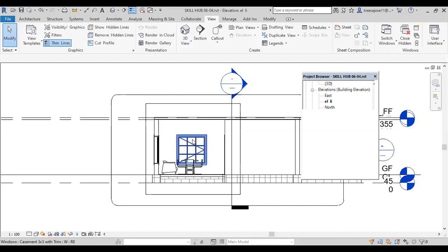In the case of kitchen, we are provided slabs. Then we need to show that actually this drawing doesn't contain any loft and all. That's why it looks like this. Maybe in the section views, you have to input the height of the slab and the slab thickness and so on. That time the furniture may disturb that view. That time you have to hide the furniture, or control the line weights.